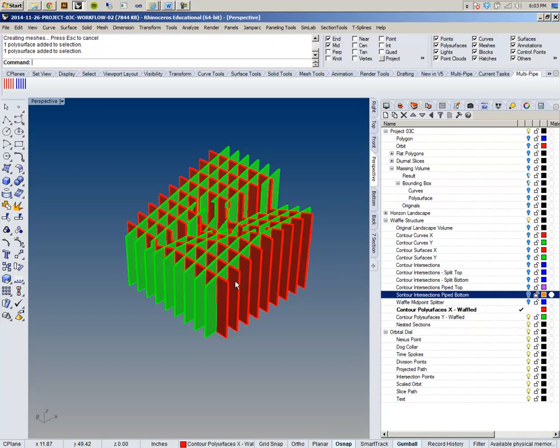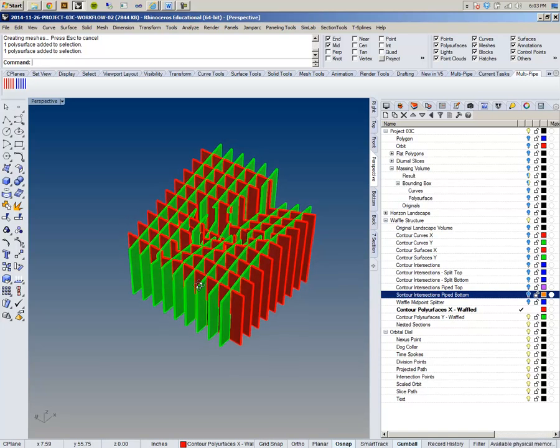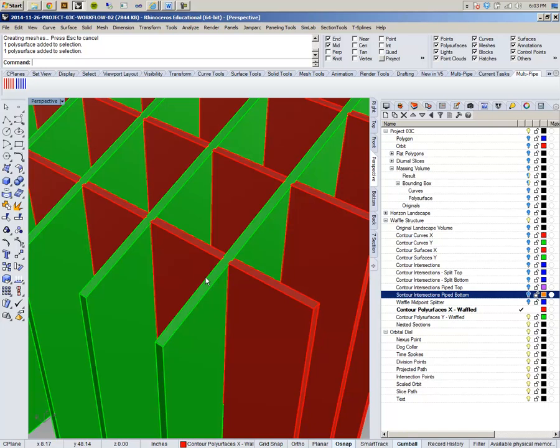So it's a little legwork, but look what you come out with. I mean, this is there in terms of the logic. You're always going to have the materiality to deal with, so be extra careful when you're measuring the thicknesses. Another thing you could do, if you're having issues with your solid, is overshoot it a little bit when you do the multi-pipe and the diameter. You can give yourself a little more space, or maybe a little less space if it's too loose.